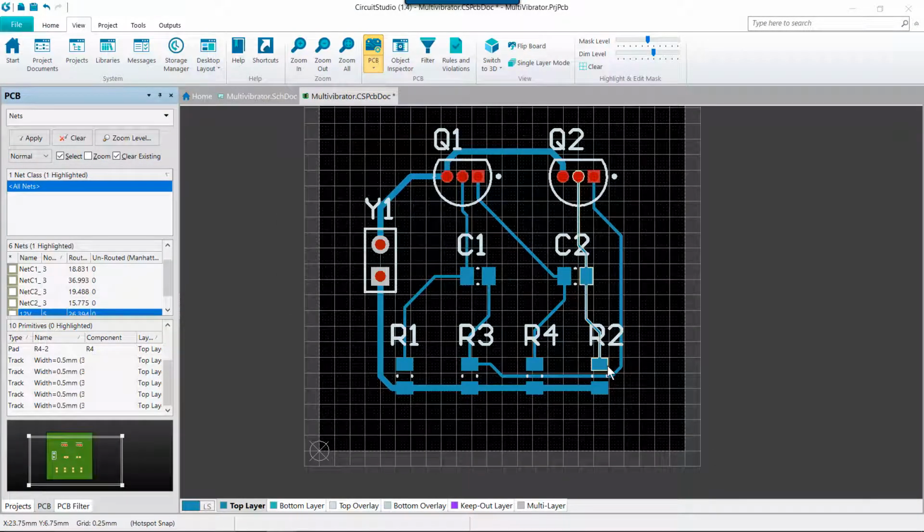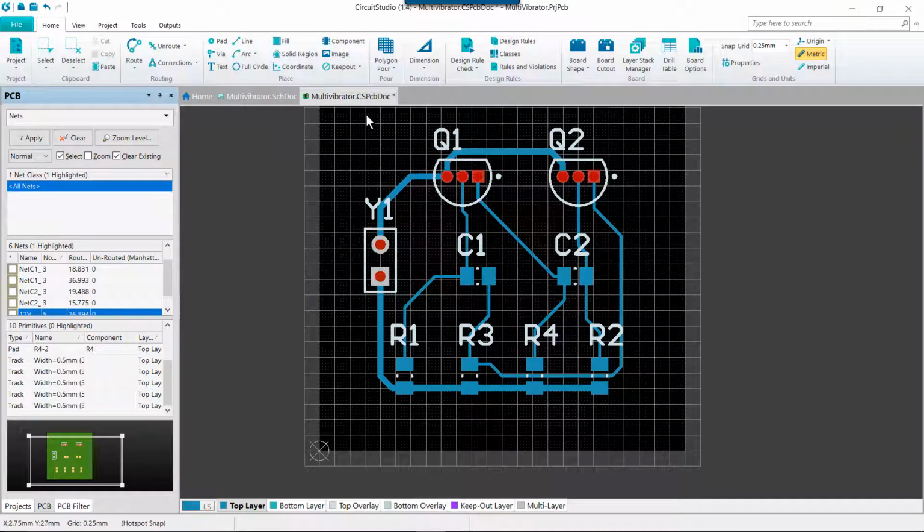The design is checked for violations by running the design rule checker. Click on the design rule check button on the home tab of the ribbon to open the dialog. Both online and batch are configured in this dialog. Now this section will not have defined exercise steps, but you should be able to follow along with me or read through the provided documentation to glean the steps that you're going to need to take from within the discussion.